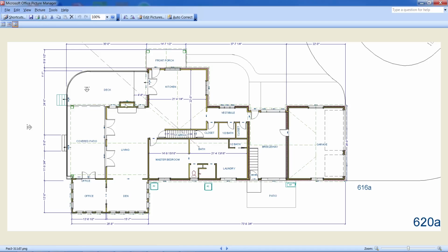Now this firebox, I'm showing it wider because of how the roof builds and how that interacts with the dormer above it. I'm showing this wider than it needs to be for what your diagram shows. This diagram here, at 620A, is shown built off of some 42-inch wide, and maybe it was even wider than that. I did not make a note of that. But in any event, you have plenty of width as far as that goes, and as much depth as you want as well.